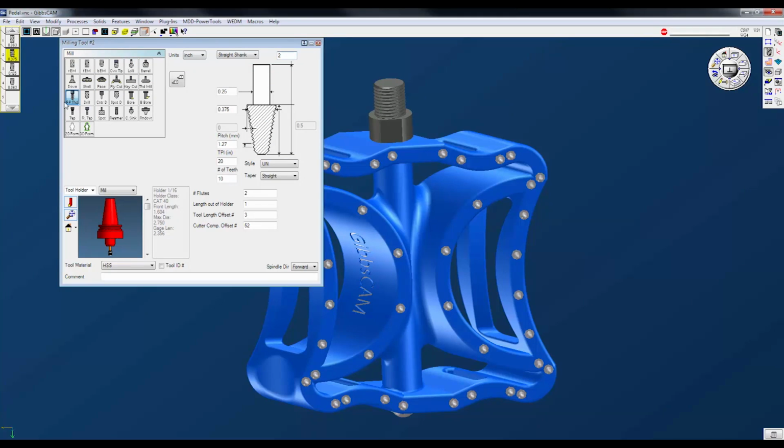We can see here that we've added a full profile tool option. So if I zoom in down here, you can see that I can define the full tool. The nice thing about this, it can support anywhere from 1 to the full depth of the threaded tool, depending on how many teeth you have. The other nice thing here is we can define tapered threads, pipe threads or other threads, different thread styles.